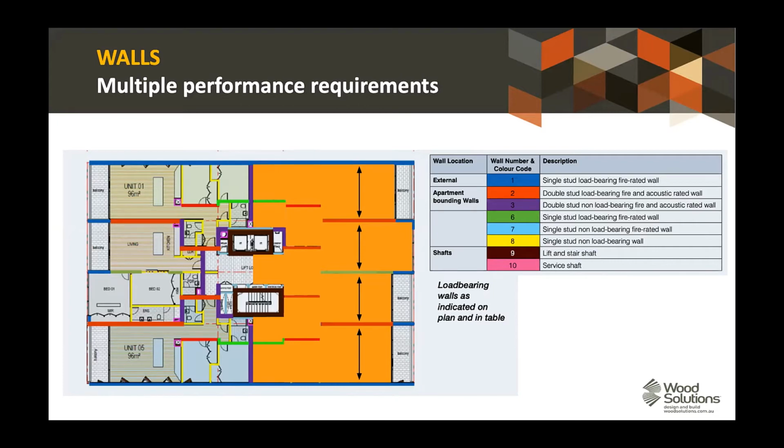Now, in many other cases, such as the acoustic performance between adjacent units, the acoustic performance requirements are set by client or BCA, and client requirements are usually significantly more stringent than the BCA requirements. And the most cost-effective solution in many cases is a separated stud. So you can start off by marking up this plan right the way across the board to say, actually, between units, we've got separated studs. We have 2 leaves of wall, which will give us our thickness. And we'll also start to define where we can then get bracing.